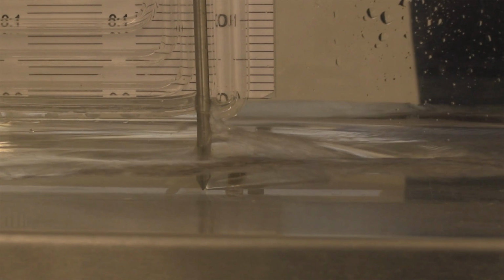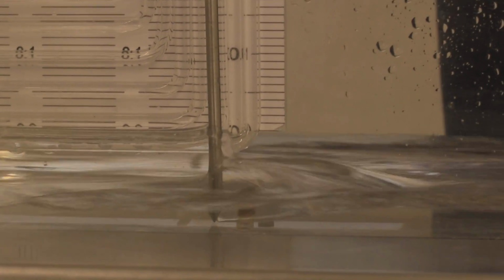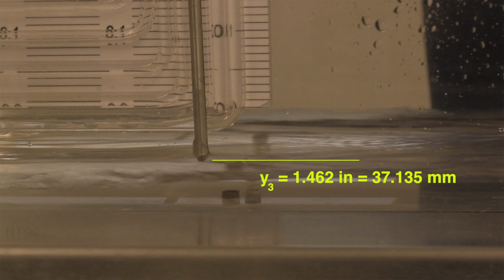Note that the point gauge is at 0 at the bottom of the flume. Now we're going to measure the downstream flow depth Y sub 3. Y sub 3 equal to 1.462 inches or 37.135 millimeters.